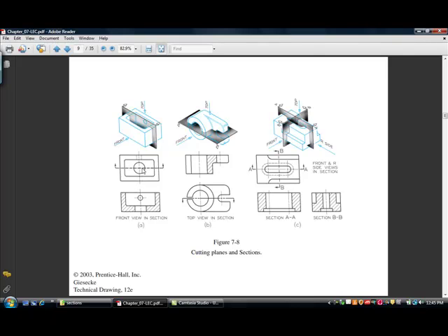It's simple enough to draw a top view of the object and then a section of the object, and that might be sufficient to describe the object completely, because a side view would then just be a rectangle, which may not be necessary. You would only show hatch material where the actual solid material is being cut. Another illustration is where this object has a gap and you're cutting only through the solid material that's in this little L shape.